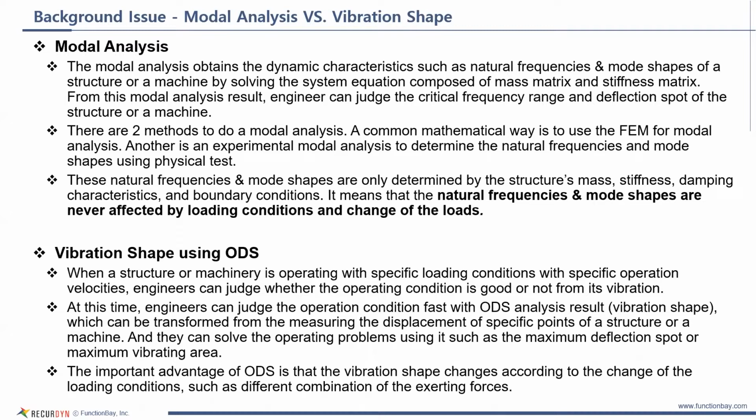Here are possible vibrational modes, and then the actual behavior of the structure, looking at the combination of excitation of the different modes and so forth, is going to be particular. But as far as the modal analysis, that information isn't considered. It's just saying here are the possible vibrational modes.